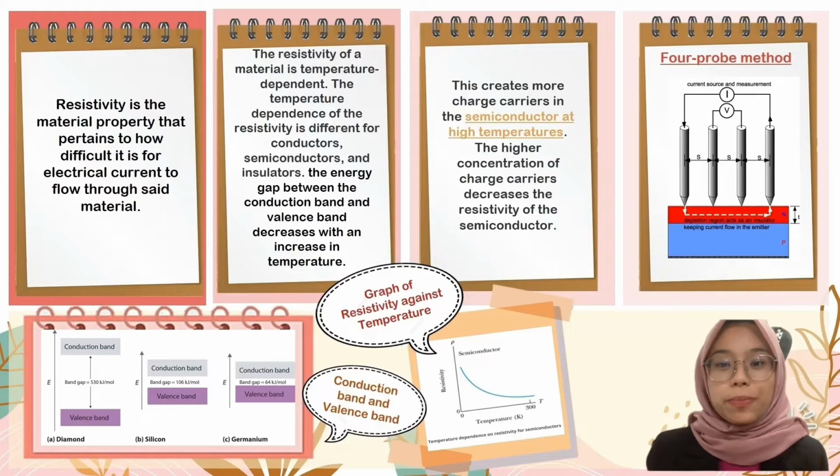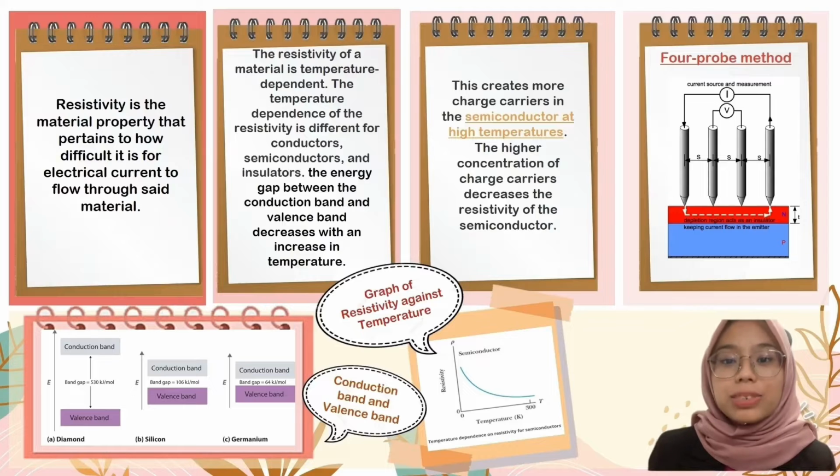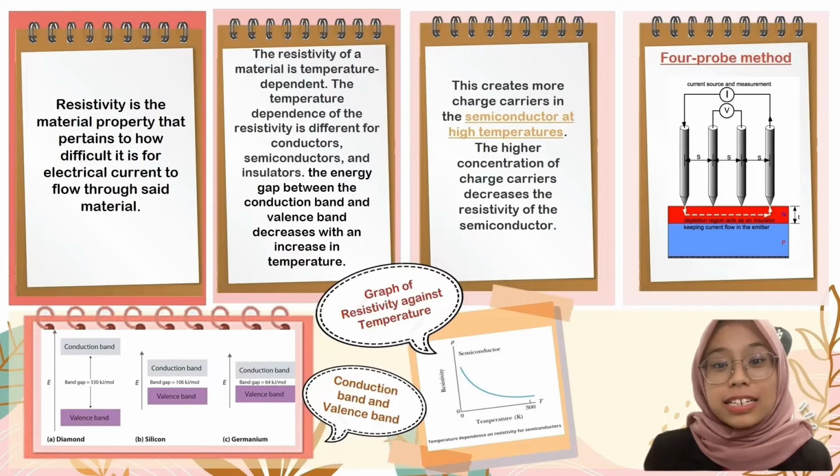We use 4-point probe method in this experiment. A 4-point probe is a simple apparatus for measuring the resistivity of semiconductor samples. Passing a current through two outer probes and measuring the voltage through the inner probes allows the measurement of the substrate resistivity. In addition, the junction between the N and P-type materials behaves as an insulating layer, and the cell must be kept in the dark.